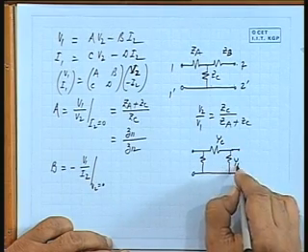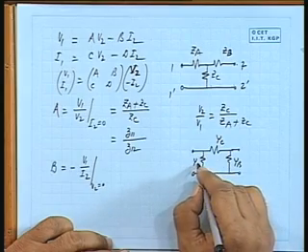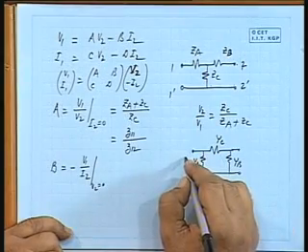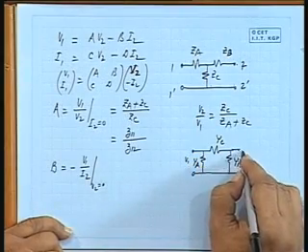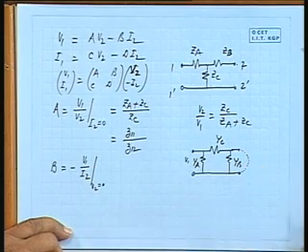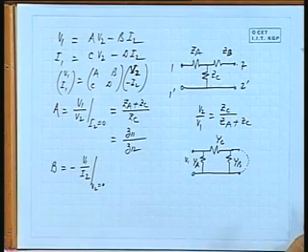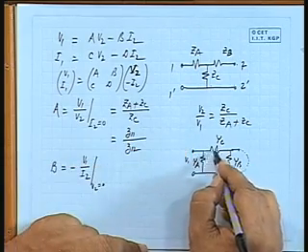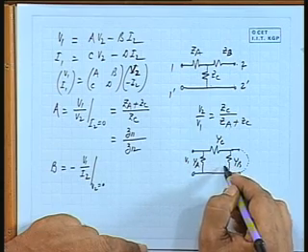Let me write in this form. So, V1 by I2, that means I am shorting this. If I short this, voltage V1 is applied across YC, YB is redundant.